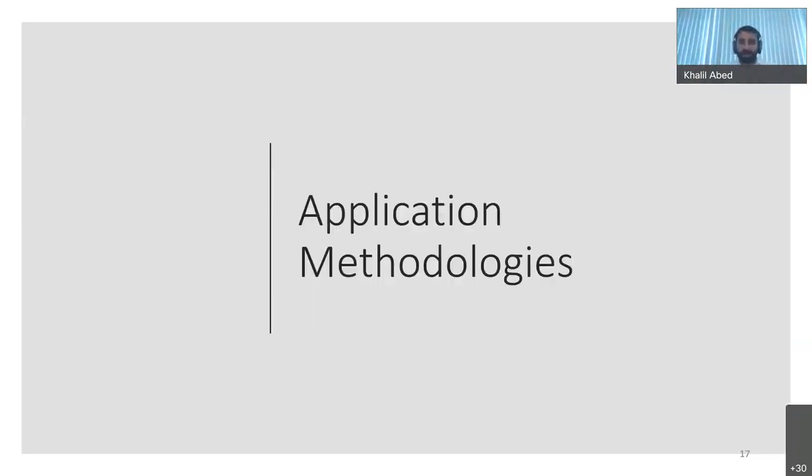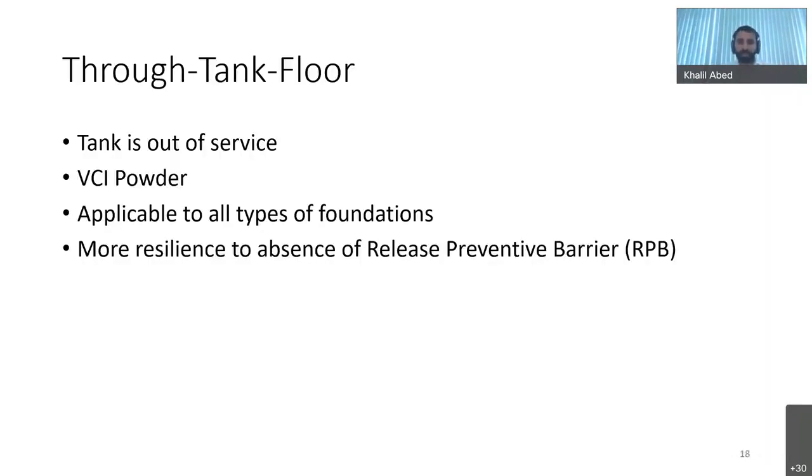Now we will be talking about the most common application methodologies for introducing vapor phase corrosion inhibitors under the tank. The first application methodology is through the tank floor. This application method is done when the tank, as it implies, is out of service for inspection, and it's applicable for all types of tank foundations.